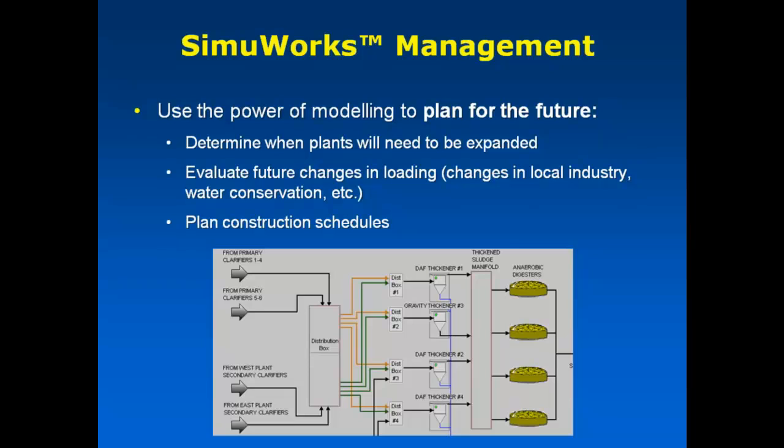We're not sure. It also allows you to evaluate what's going to happen at your plant if there is a future change in the loading, such as where a local industry may be coming in and setting up, or one may be shutting down, and that's going to have a potentially large change in your influent loading. It could also be on the domestic side, where some water pricing policy or conservation effort is going to change the concentrations and flows coming into your plant.